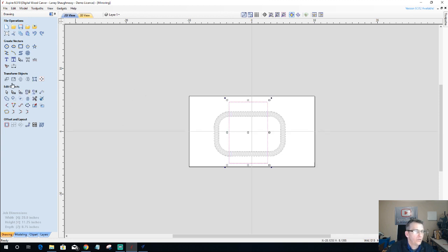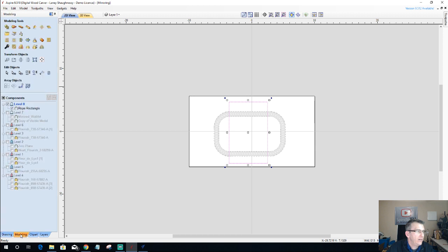If I were to draw a rectangle there, and in Aspire I can select my rectangle and my rope, and I can remove everything outside of that boundary to get rid of those two ends. So now I have two straight edges. Okay. And since there's two straight edges, I can use them and add them to that border, top and bottom.